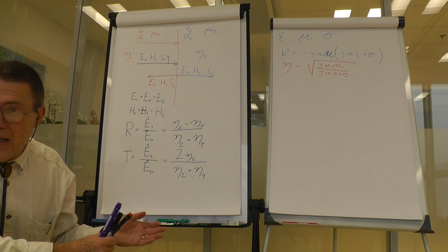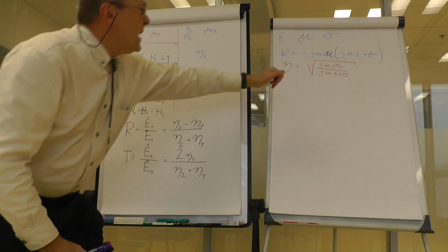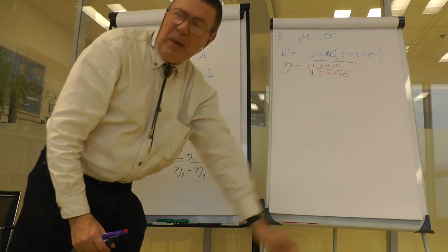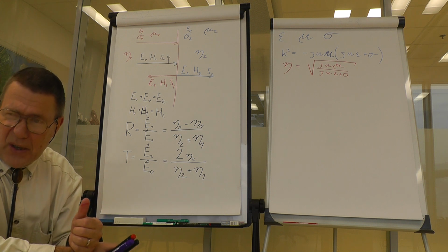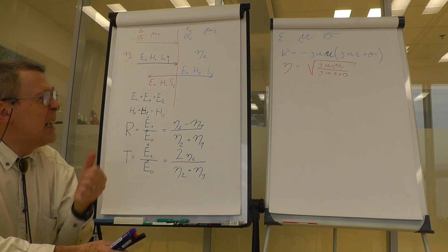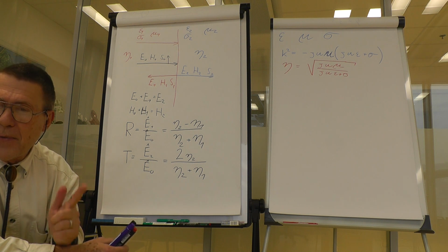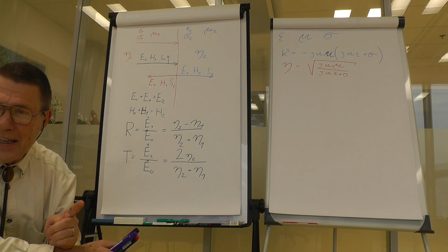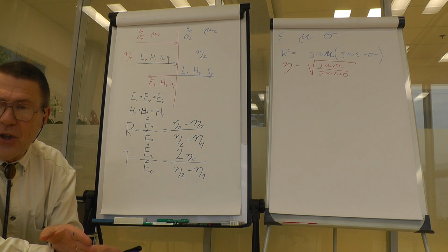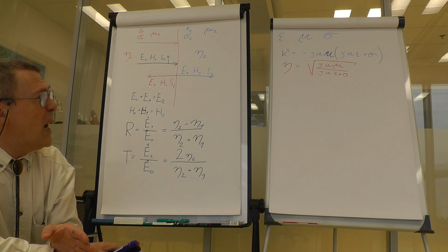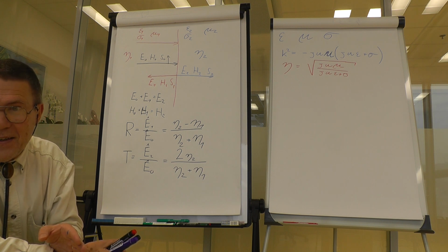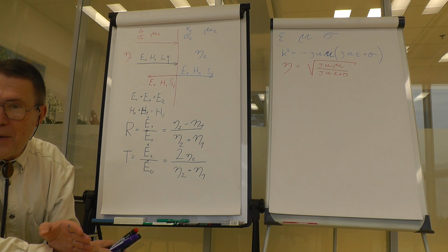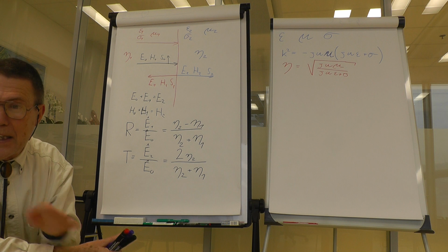conductance. And we find out those parameters, mu, epsilon, and sigma, so that they fit both situations. They give us good predictions of transmission, they give us good predictions of reflection, and this is enough. So these engineering parameters for high frequencies, in fact, are measured using transmission and reflection, and they give us good prediction of transmission and reflection, and that's all.